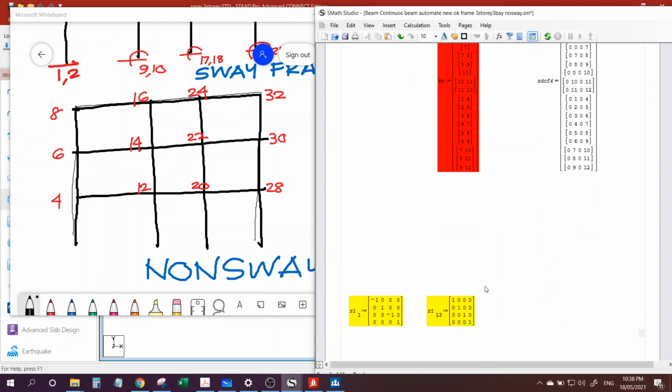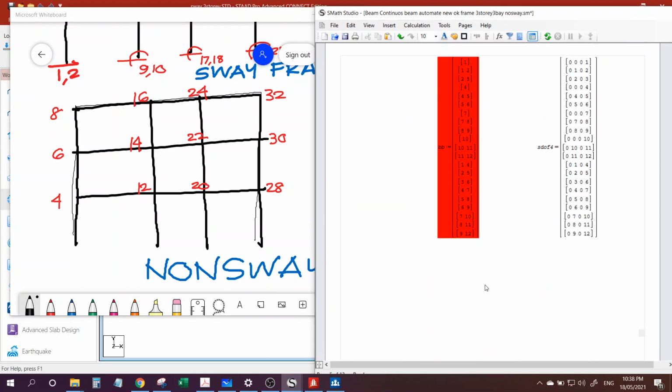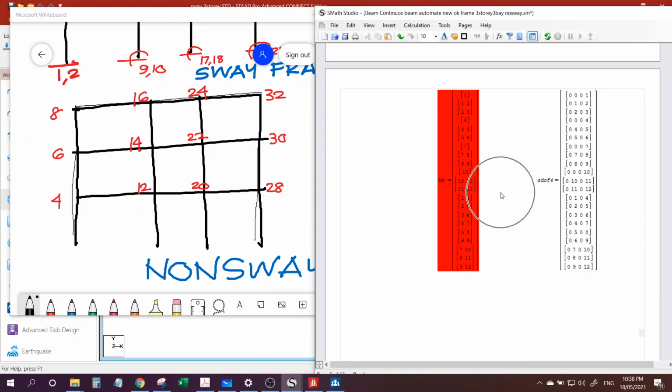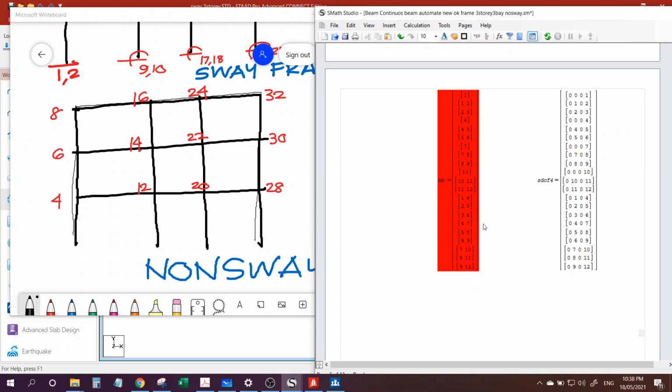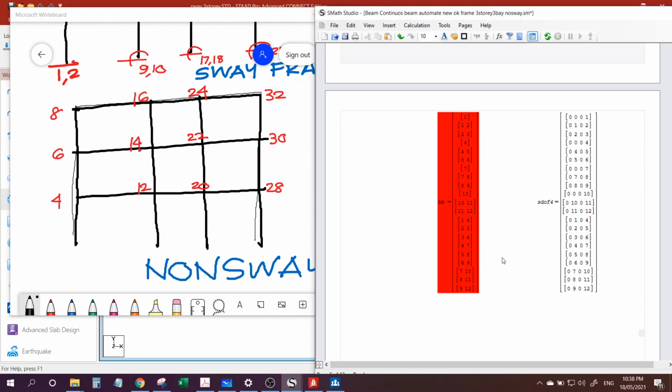And so remember, the BB matrix is the destination on our 12 by 12 S matrix, right? So remember, for example, here for member 1, the only required unknown displacement is at code 4, which is located at the first element.